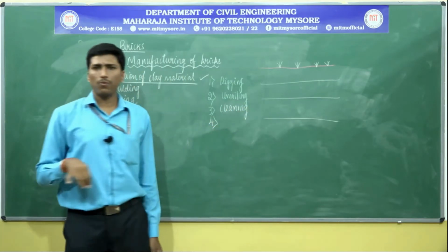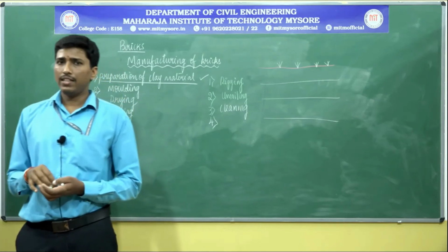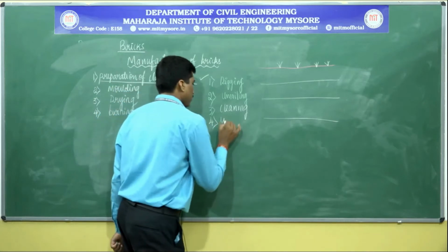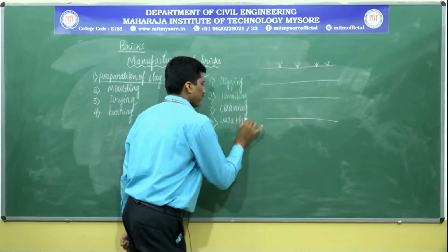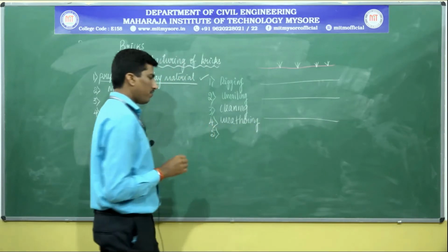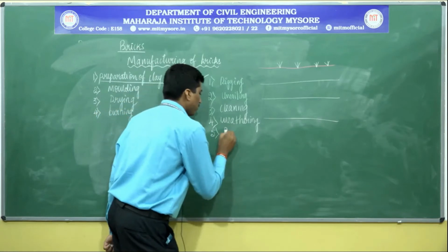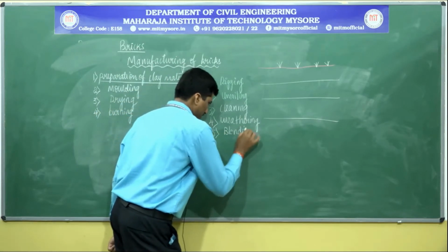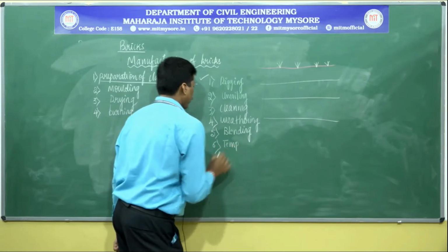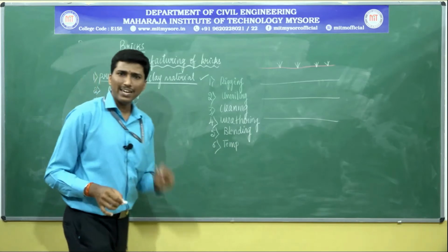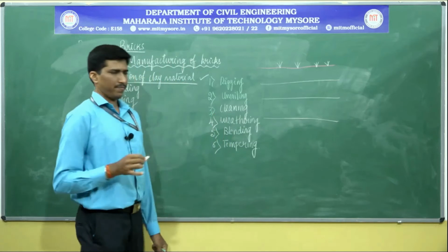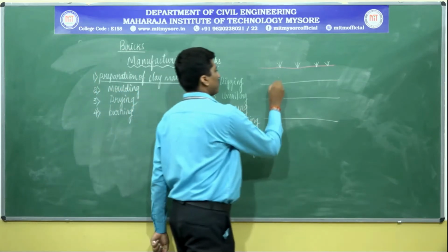Fourth one, after the cleaning, they have to be subjected for weathering phenomena, means exposure to atmosphere. Weathering. After weathering, it has to be subjected for the blending, for proper mixing of the materials. At the last stage, before the preparation of the mold, it has to be tempered. We call it as tempering. There are various sorts of the